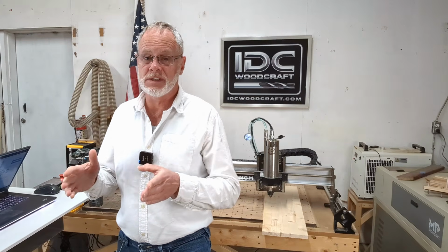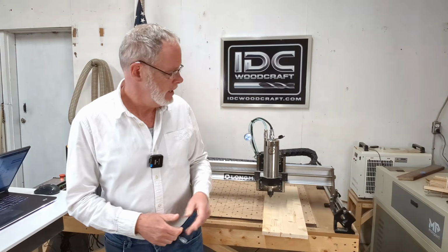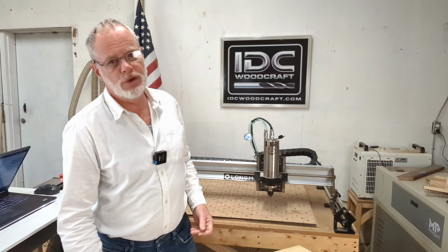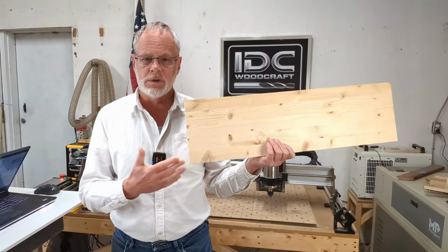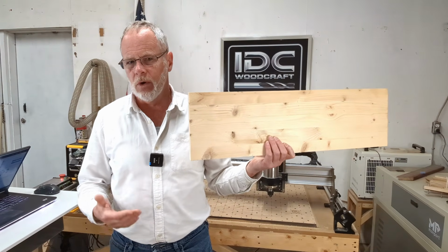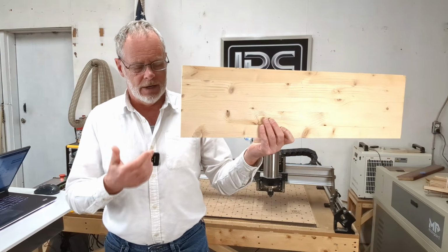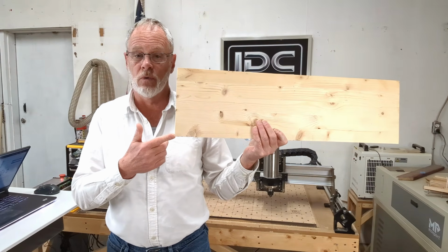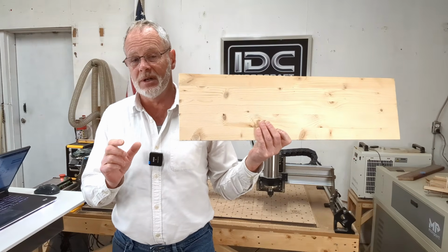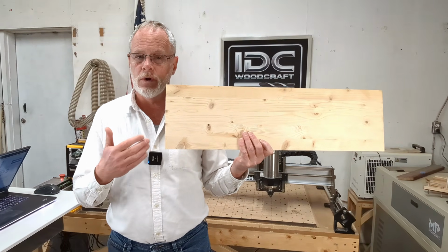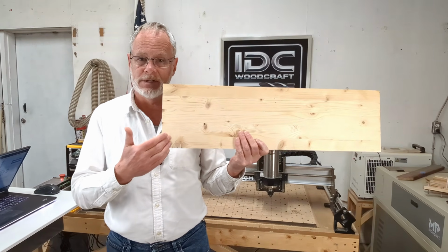And it also sets what's called your zero values. What I mean by zero values is, when you design the CNC project, you've got a corner that you're using to reference, or some position on here that we call X, Y, Z, 0. In this case, we're just going to say the lower left corner of this board. That would be the 0 reference. Those numbers next to the buttons are going to indicate where your router bit is relative to that 0 point.